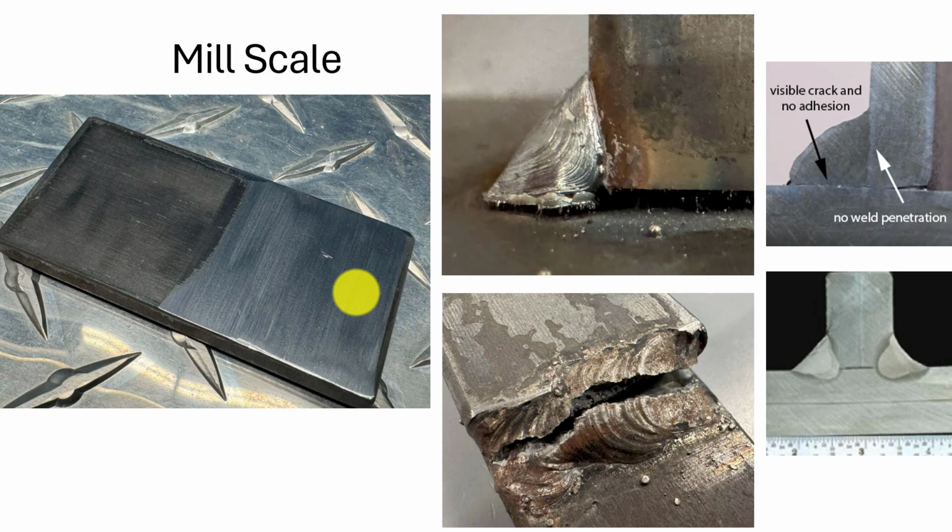Typically, we get steel that's hot rolled steel. It's going to be probably an A36 for a lot of the steels, and especially what we're doing here in lab. And it's going to have mill scale on this sample. If I look at this right here, I could see mill scale, and that can flake off, and that's an oxide. That is an insulator. We don't want to try and weld across that and get that broken up into the weld or anything of that nature.